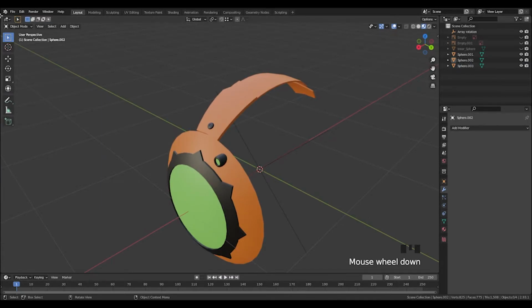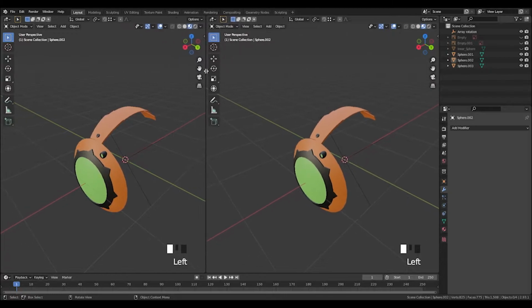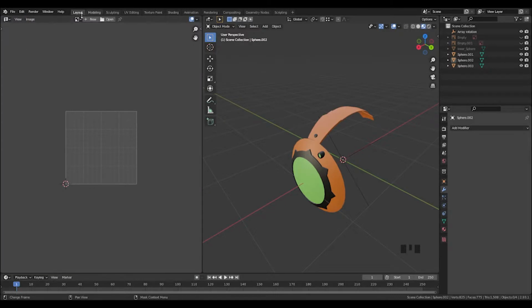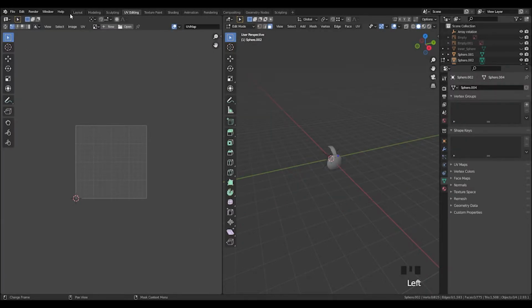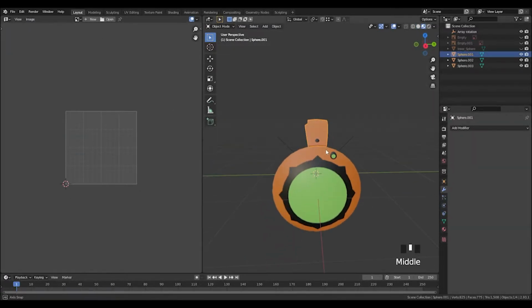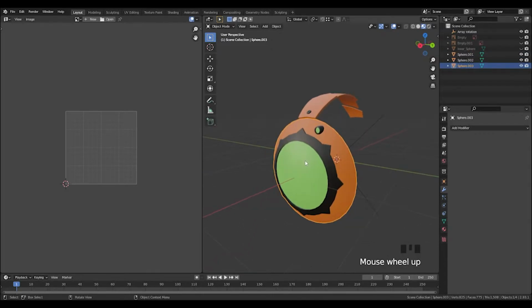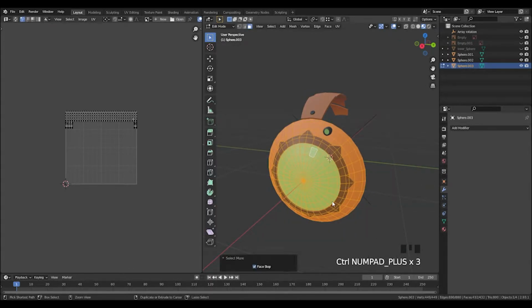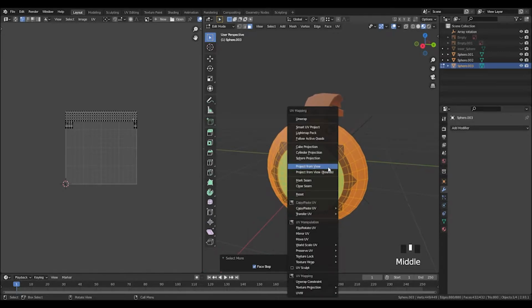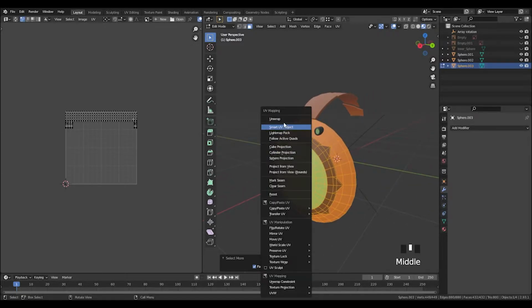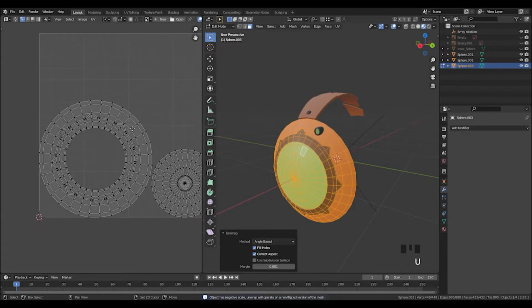If you select up at the top and drag down, we'll make a new window and UV editor. You can also just click on UV Editing up at the top and it'll get you to the same point. We will unwrap this bit first. Select the model, go into edit mode, faces, and select them all, and then press U. For this, we'll just unwrap. There we go.